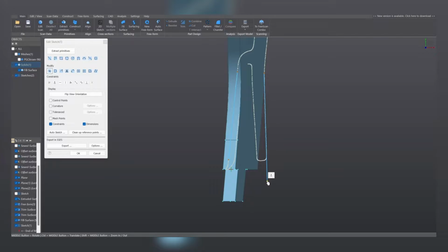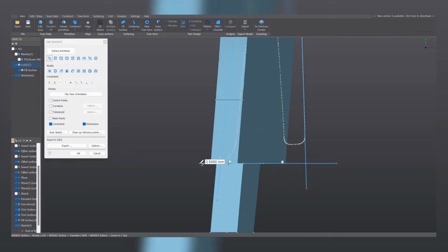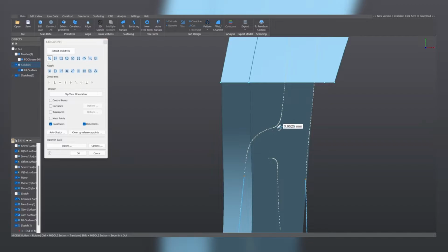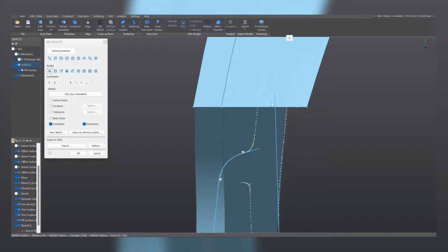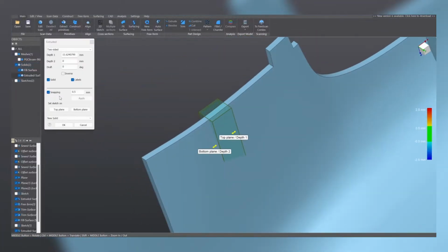We are going to extrude them. Well, we are going to extend them, sorry. And we are going to create a horizontal line on the origin of the coordinate system. And let's now join these endpoints. Now, on this side, we are going to draw a small line following this angle here. And we join these endpoints, and we even do the filleting. And now we can extend these lines a little bit more and connect them together. That's it. Click on OK. And now we have a closed sketch that we can extrude and obtain a solid.